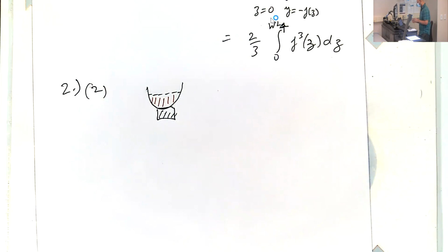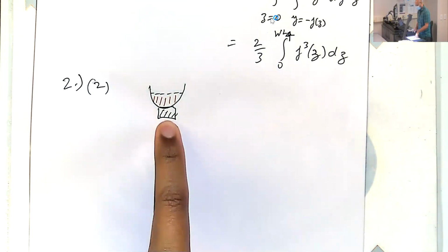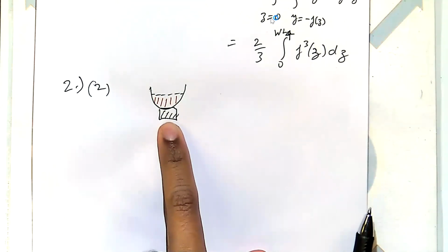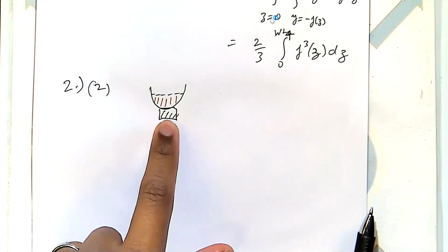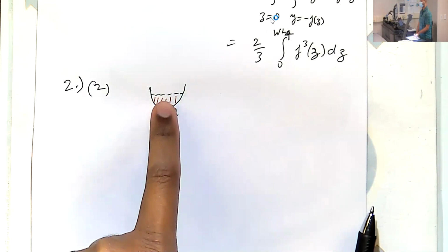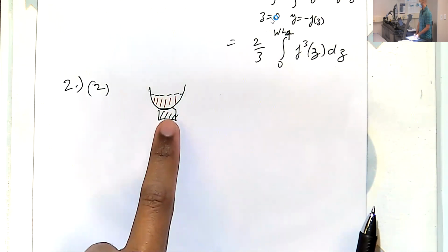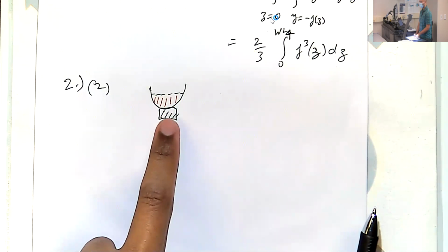Well, doesn't it depend on whether the appendage has got a density greater or less than the water? Correct. So there are several things happening. You have added a mass to your boat, and you've changed the submerged volume by adding this thing.